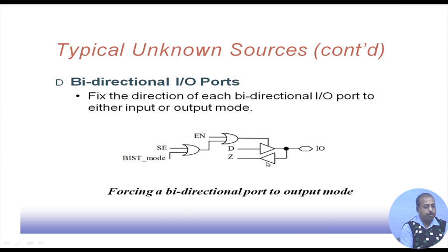Similarly, you can have some circuitry on the lower side for this Z. So, we can control this line to be always input in the BIST mode. Whatever is required, whether we want to sense a line as input or output, we can put a control over that.